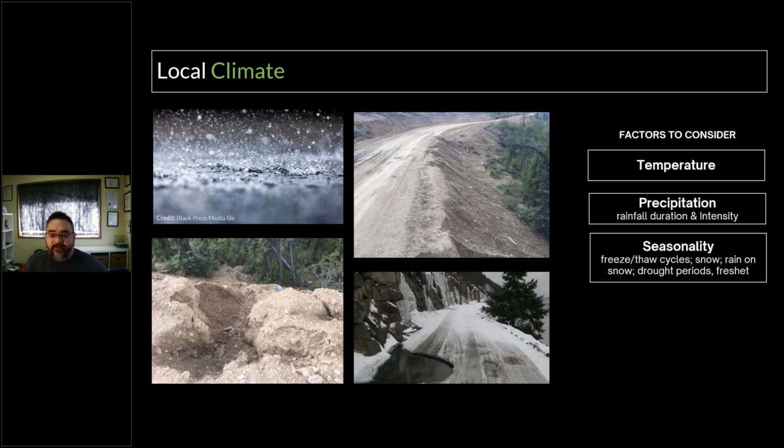But you have to understand things like peak flow and what impact that's going to have. On the coast here, it's early fall or winter storms on these short, steep watersheds. In other areas, it's going to be more driven by snow, and that's going to impact how you design and your seasonality of use.